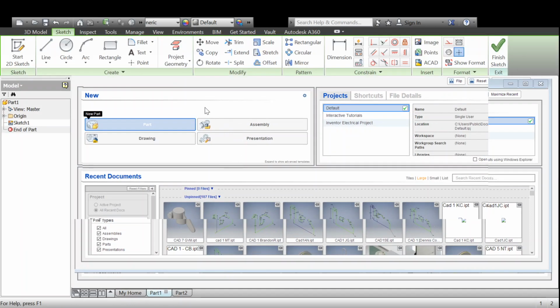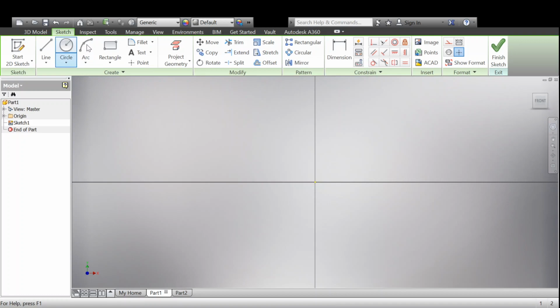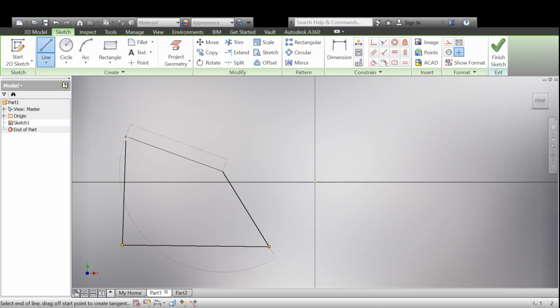So we're going to look at a 2D sketch first. And all I want to do first is start by talking about some of the three-dimensional features that exist. And to do that, I want to start with a 2D shape. So I'm going to start a 2D sketch like I've done already. I'm going to choose for now just the line feature. Okay, I'm going to simply draw any sort of polygon, and I don't really care what it actually looks like right now, as long as that polygon is closed. So remember, to guarantee that it's closed, I want that to turn green so I know that I'm on the same vertex at the very end. So when I click here, I've got at least a closed polygon now.